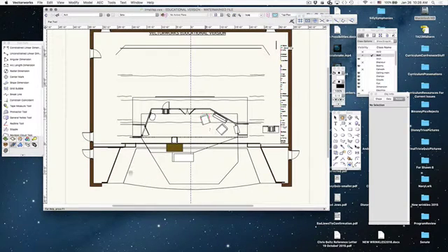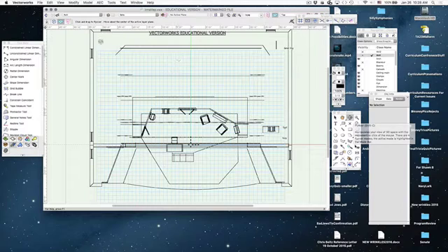So this is a ground plan of our theater. Vectorworks is a 3D software application. While this looks like a ground plan, I can click this tool, which is our flyover tool. When you hover over something, the words, what it is, comes up. It says flyover Shift-C. So if I hold Shift and C, it will select that. Or I can click it, or somewhere up here in the menu, I can get to it.